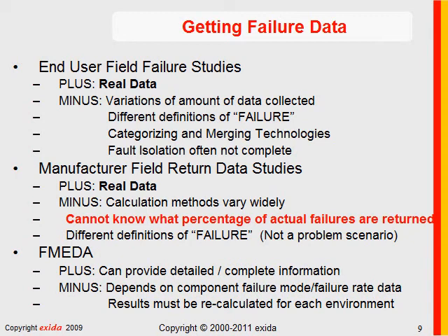Often it's higher at the beginning of the operating life. It drops and continues to drop during operation life, and then at some point it starts to go up rapidly, and that's the point which we call end of life or end of useful life. Safety and reliability modeling typically assumes a constant failure rate, which, if the number is chosen properly, is a very conservative assumption that drastically simplifies the math, in combination with an end of useful life.